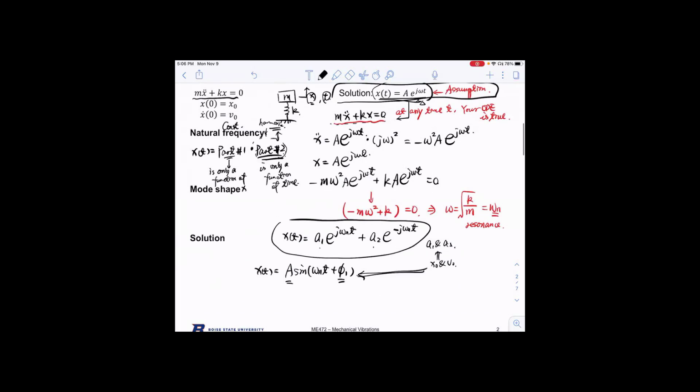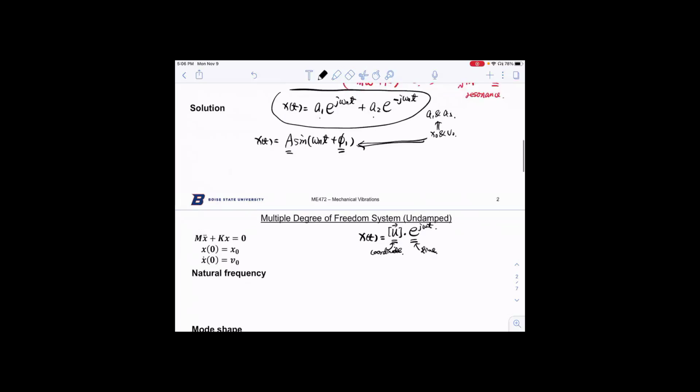Very similar to the single degree of freedom method, we just calculate your x(t) double dot. The benefit of variable separation occurs here. If you want to calculate time derivatives, your first term has nothing to do with time because we already separated these two variables. The first one you can consider as constant, and you just need to calculate time derivatives for the second term.